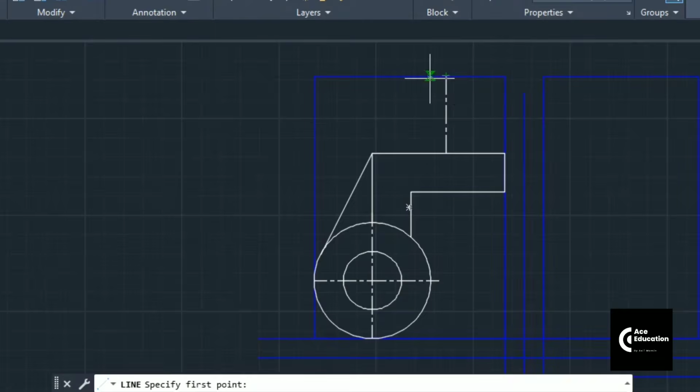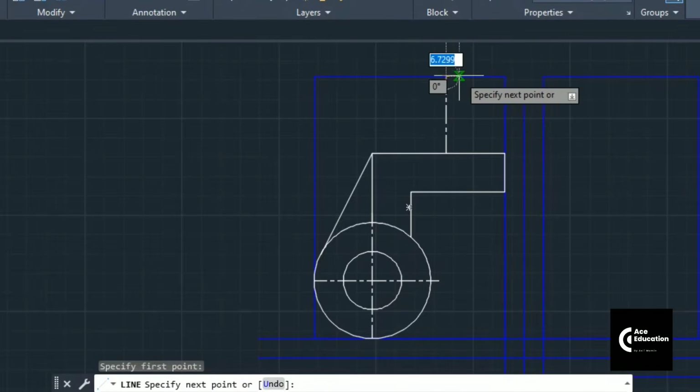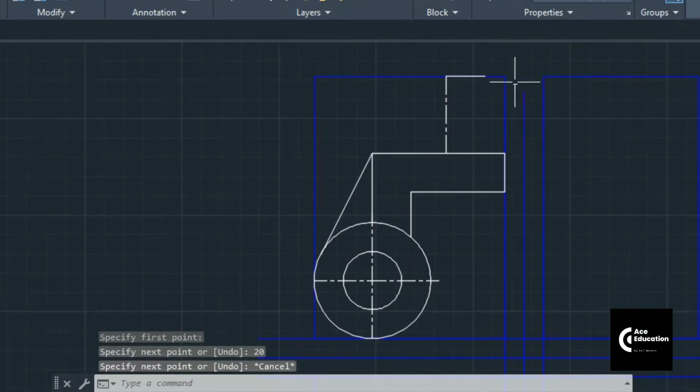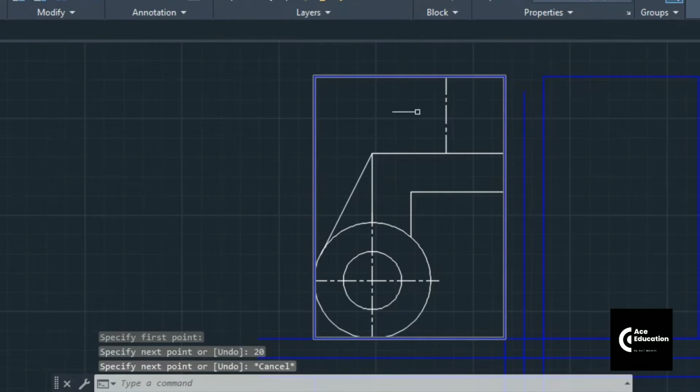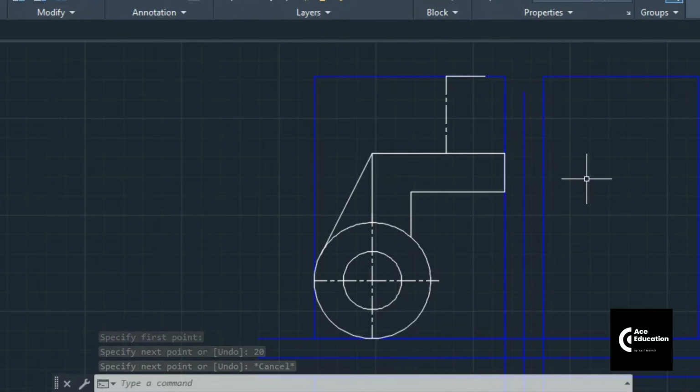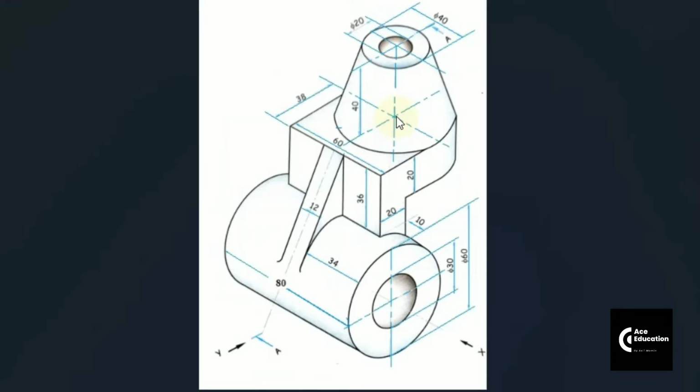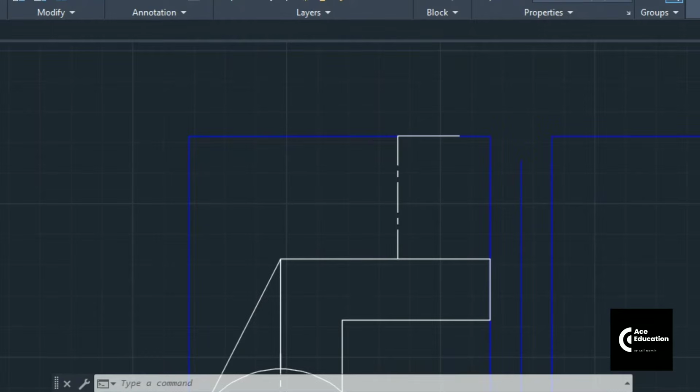and from this center point on the top plane, we are going to draw 20 mm on the right. Similarly, 20 mm would be towards the left. So that the total diameter would be 40 mm. We have a radius of base circle as 30 mm and a radius of top circle as 20 mm. So this is a 20 mm radius, this is a 30 mm radius. Join both these ends by a straight line.